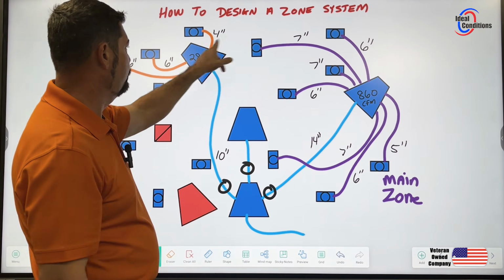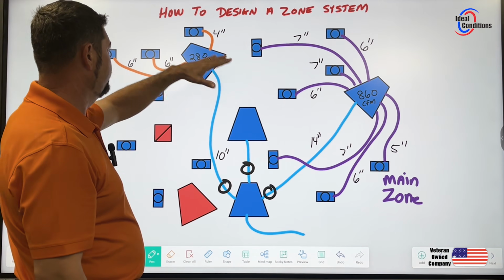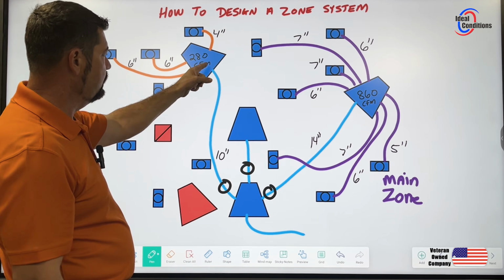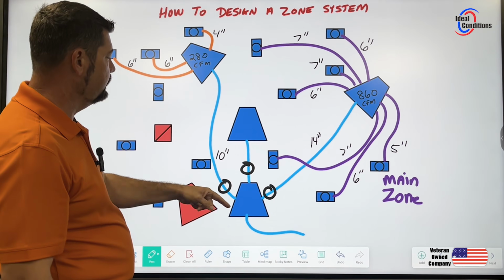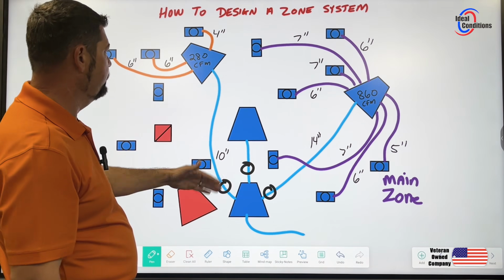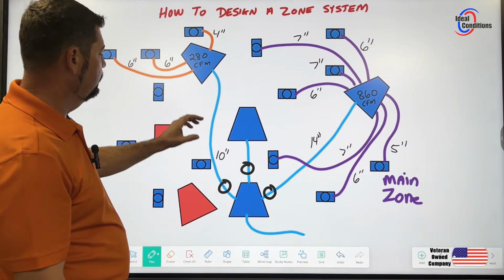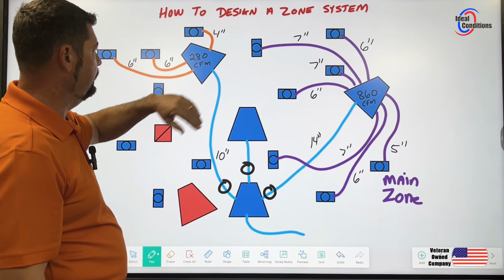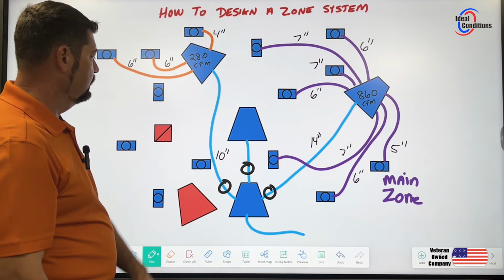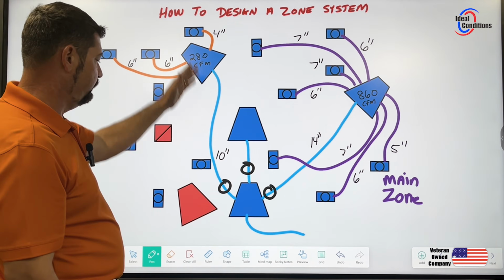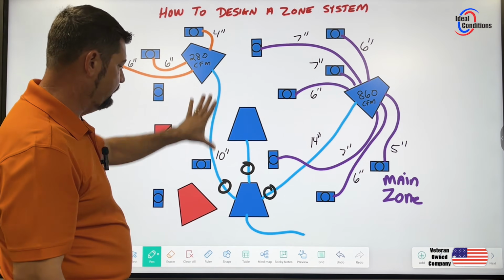So the 7 that we pulled off of it dropped 150 CFMs off that box, which now we don't need that trunk line. Even though it was already coming off of here, we brought it down to here. But that doesn't mean that you can take the 12 off of here and splice it and come back here, because then that zone will be oversized. You need to size it for the CFMs that are going to be on that box. We know we have 280 CFMs, and the 10-inch falls within that because we'll get 350 CFMs at a 0.5 static pressure on that flex, and that's how we're going to do that.